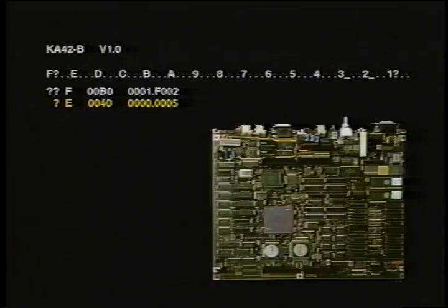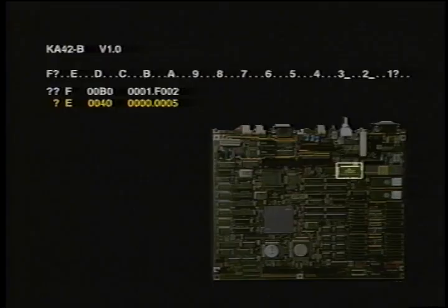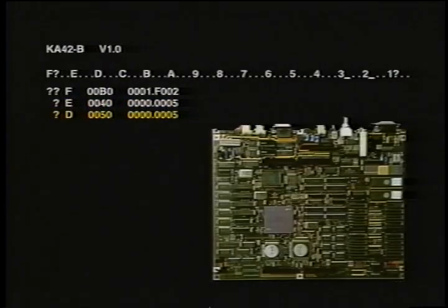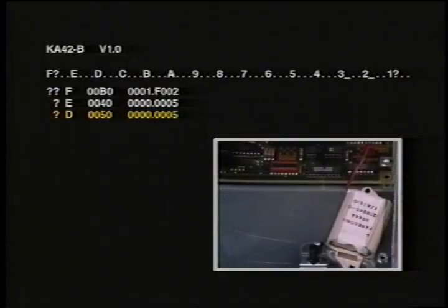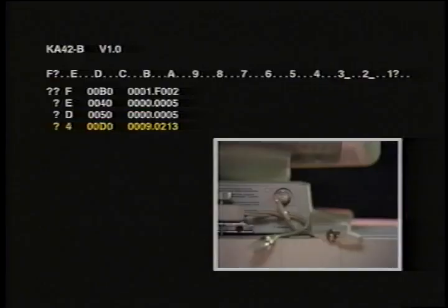Many soft errors are more likely to occur when a system is first installed. For example, the time of year clock has not been set by the operating system software. The battery is low. This condition changes shortly after power-up. The battery fully recharges in 17 hours. A monochrome monitor is attached to a system with a color graphics option. Terminate the red and blue connectors.